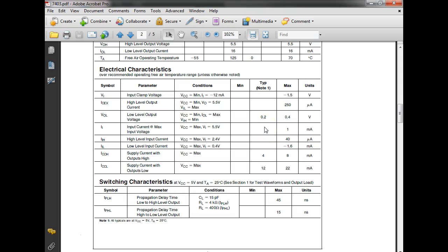So this is why they don't put fan out in data sheets: what we need to know is how much output current these guys can drive, and then the required input currents of the gates it's trying to drive. Does that make sense? It varies with each gate, right?